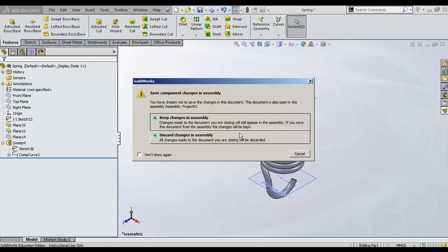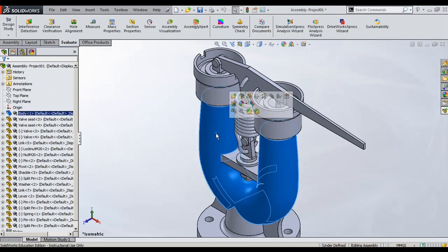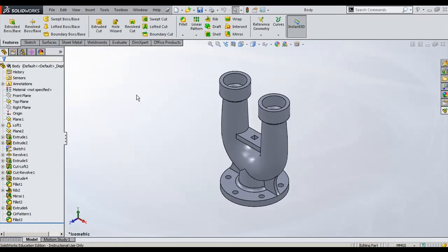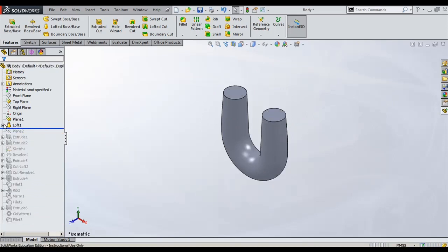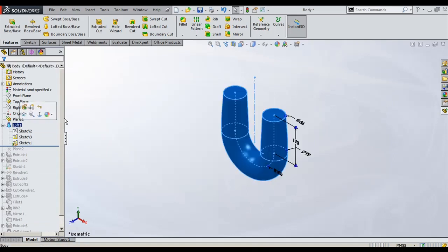Let us see how a ram bottom body is created. Here the remaining commands you see are the same, but there is one thing we need to clarify, how this centerline parameter is used in the loft command.